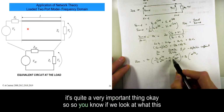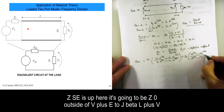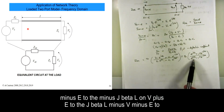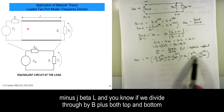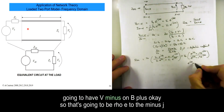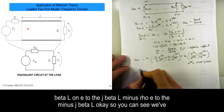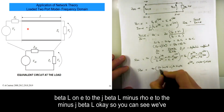So if we look at what this ZSE is up here, it's going to be Z0 outside of V plus e to j beta L plus V minus e to the minus j beta L on V plus e to j beta L minus V minus e to minus j beta L. And if we divide through by V plus both top and bottom, it's going to be something like Z0 e to the j beta L plus V minus on V plus, so that's rho e to the minus j beta L, on e to the j beta L minus rho e to the minus j beta L.